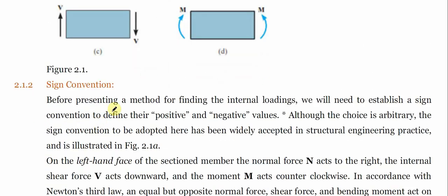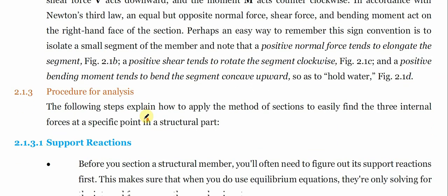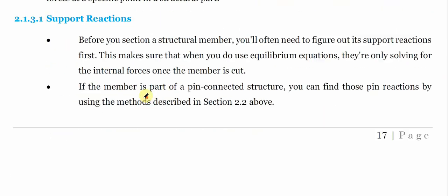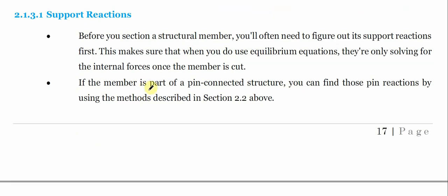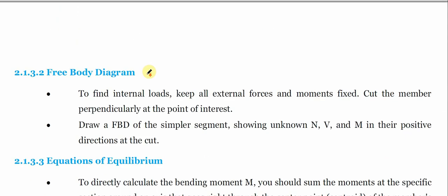When I say sign convention, for instance, when you are treating a member, if you are adopting a sign convention that all clockwise forces are positive, you must maintain that sign convention till the end of that particular problem that you are solving. You can't just change the sign in the middle of any calculation. Now we have support reaction. Depending on our support reaction, maybe simply supported, roller, pin supported or fixed, the support condition has a lot to play.